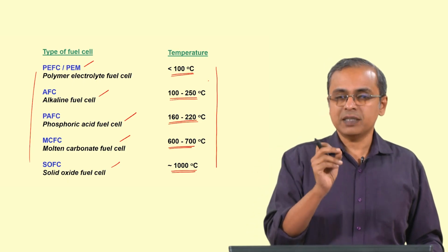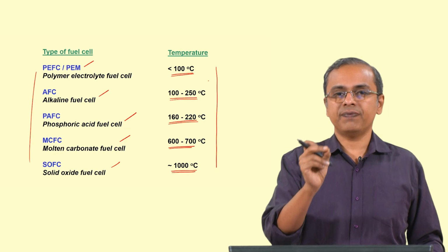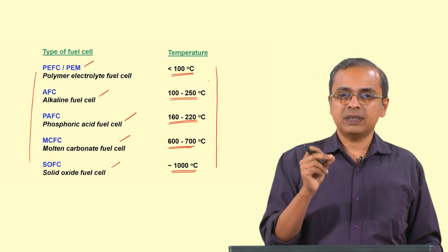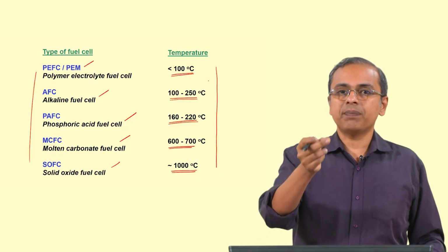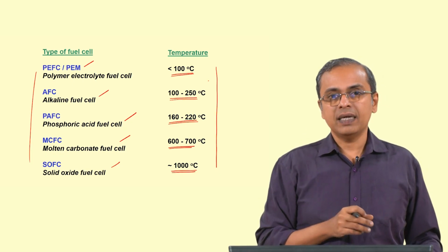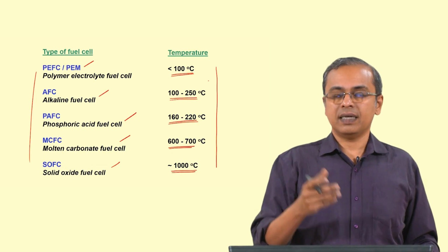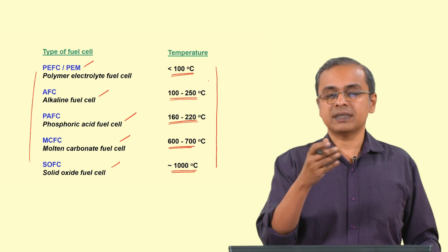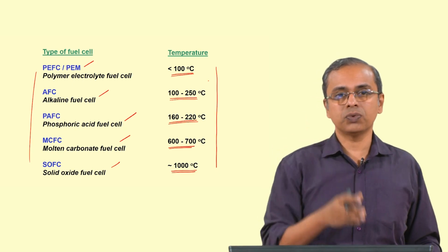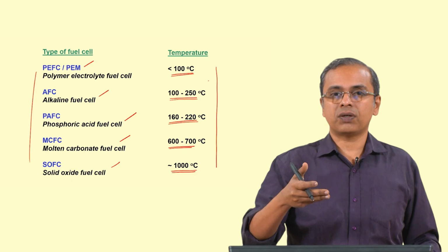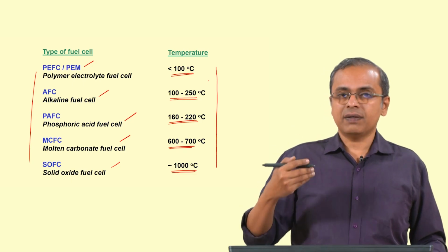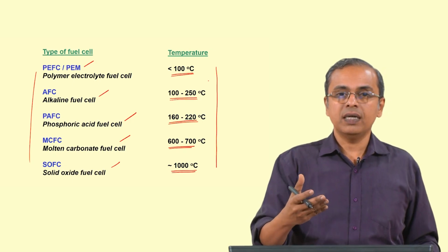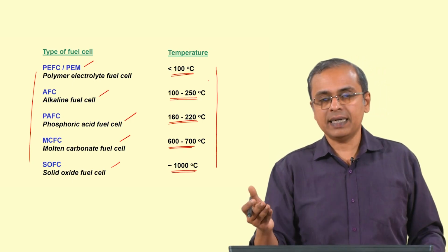Okay. So, in this context, it is very different from electronic conductivity. If you take any wire, any metallic conductor which is conducting electrons, if you raise the temperature of that material, it will typically increase in resistance because it increases the number of collisions that the electron will face as it tries to move through that conductor, and therefore it slows down the electron. So, typically this is seen in the form of an increased resistance to the flow of electrons in the external circuit. So, this is what you will see when you have any metallic conductor.